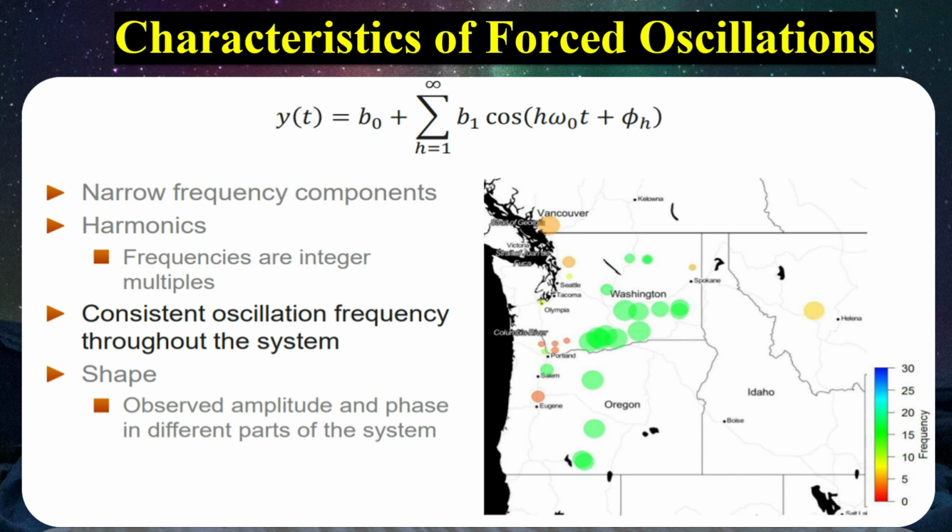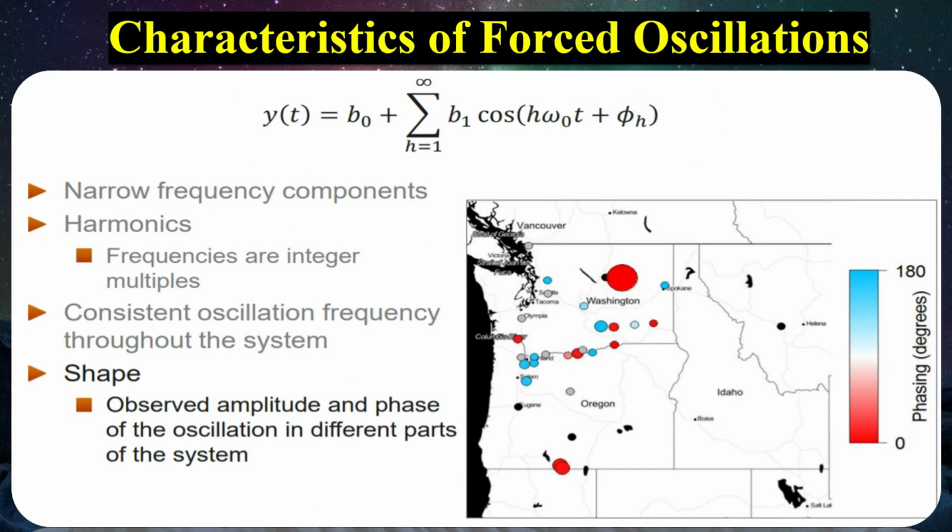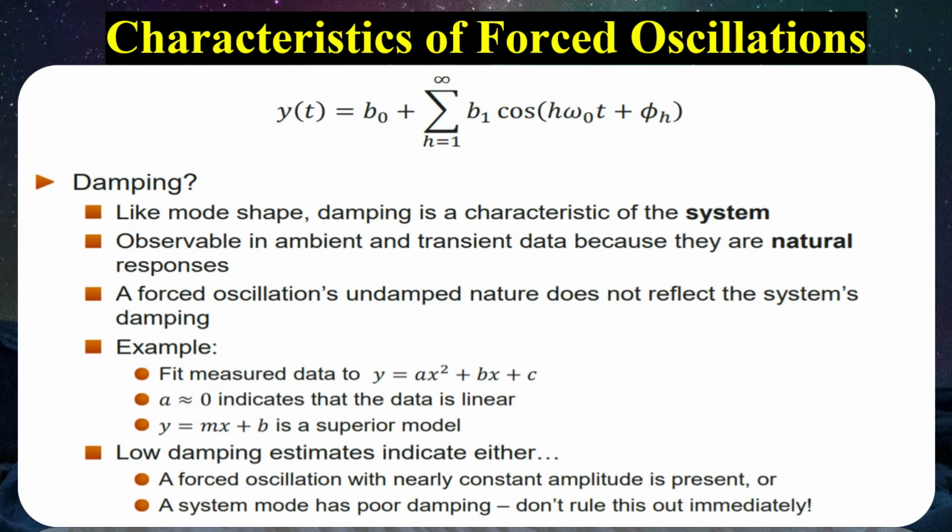3. Unified Power Flow Controller UPFC. A UPFC can be used to shift the resonant frequency, effectively mitigating the steady-state response of a forced oscillation. 4. Static Synchronous Compensator with Energy Storage, Enhanced StatCom. This device can be used to modulate active and reactive power, effectively eliminating forced oscillations propagating from the disturbed area to other areas. 5. Cybersecurity measures. As forced oscillations can be caused by cyber attacks, implementing robust cybersecurity measures can help prevent these types of disturbances.